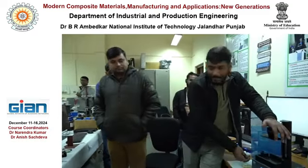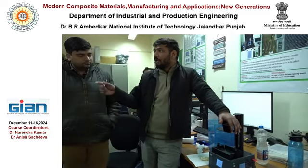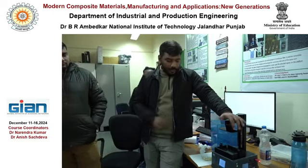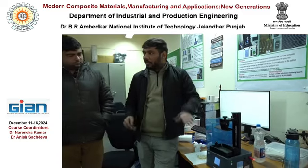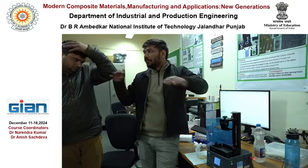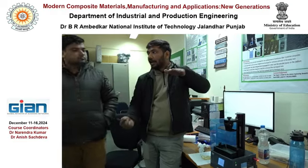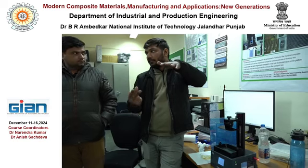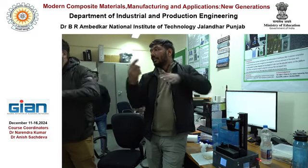So the UV light comes in the form of a projector, and the intensity is in milliwatts, like 2 to 3 milliwatt per centimeter square. Intensity is low, and the platform and the bed are there. If you maintain a gap between the platform and bed of 0.01 mm, the liquid will fill in between them, and you put a projector, means UV light. After coming in contact with the UV light, this material will get solidified.